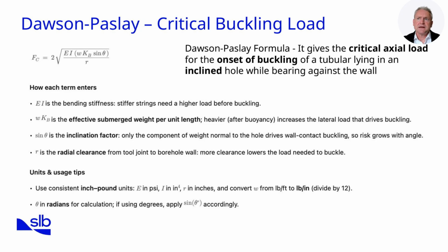The Dawson-Pasley formula is one of the most widely used methods for calculating the critical buckling load of a drill string in an inclined wellbore. It provides a practical way to estimate when sinusoidal or helical buckling will occur, based on the balance between pipe stiffness, weight, clearance, and inclination. In simple terms, the formula shows that buckling occurs when compressive forces exceed the pipe's ability to resist lateral displacement.